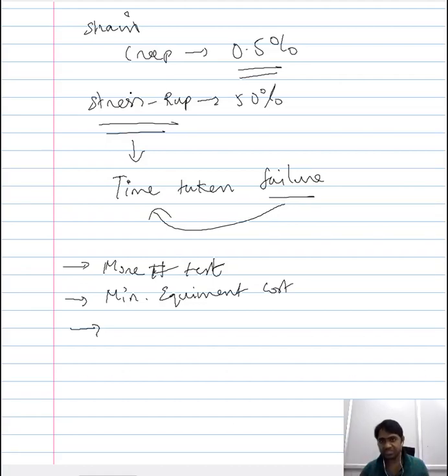However, if we have an application setup wherein any amount of strain is permissible, and the only factor that concerns us is the failure, then the preferable test that can be performed on the material is the stress-rupture test. So we've seen that the stress-rupture test is similar to the creep test. The only difference is you use a significantly high stress condition. So this means your steady state rate is accelerated and the overall test finishes off in a very small duration of time.